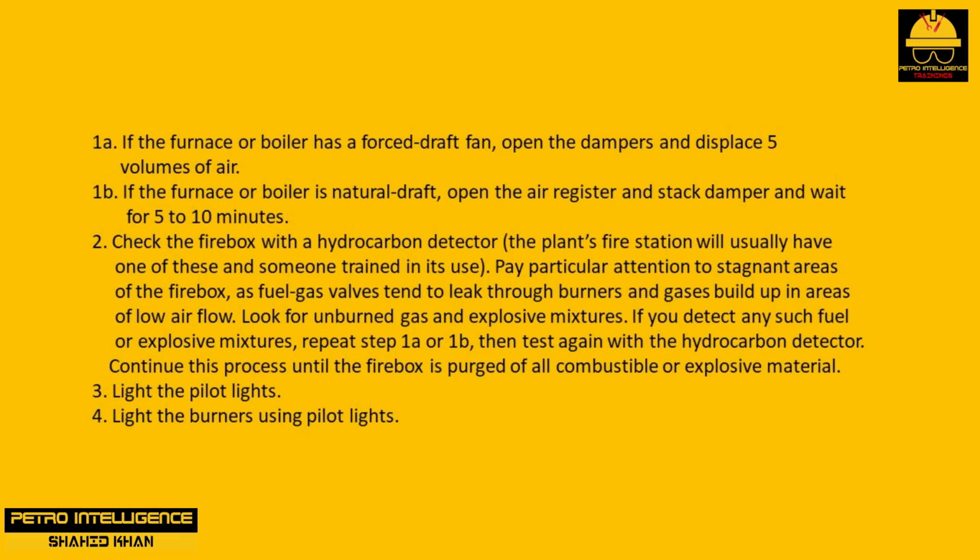Pay particular attention to stagnant areas of the firebox, as fuel gas valves tend to leak through burners and gases build up in areas of low airflow. Look for unburned gas and explosive mixtures. If you detect any such fuel or explosive mixtures, repeat step 1A or 1B, then test again with the hydrocarbon detector. Continue this process until the firebox is purged of all combustible or explosive material.